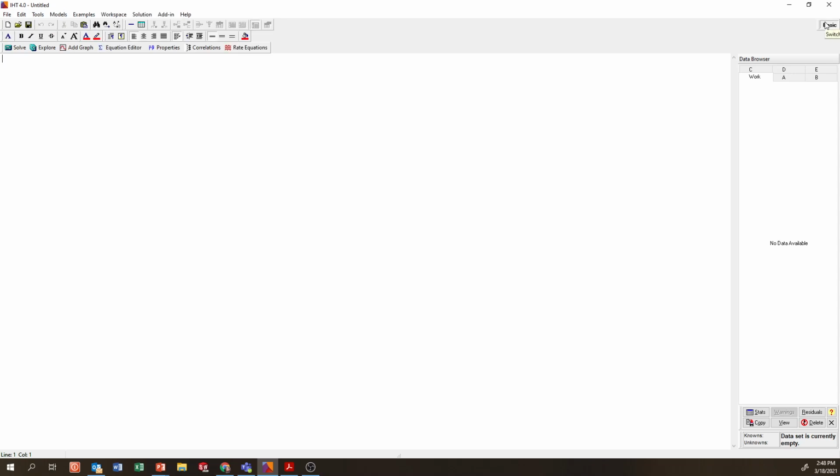And this problem in particular, we've got a plate that we know some things about. Looking at our problem statement from the book, we have this plate that's 25 millimeters thick, comes out of our process at 600 degrees C, and we need to cool it down. We're wondering whether we should cool it on both sides or just on one side using a stream of air that is available to us. So we're going to compare those two and see what we've got.